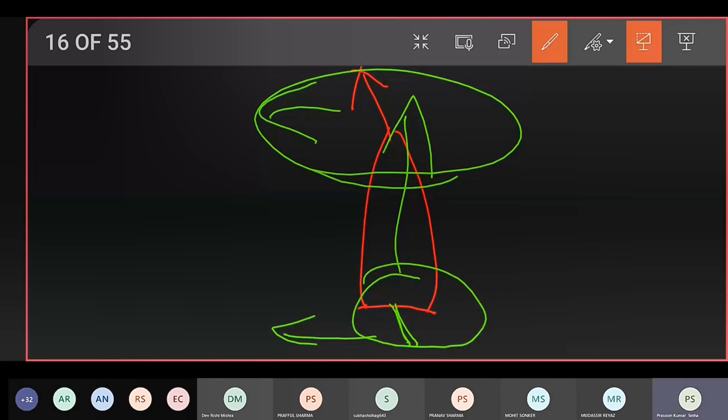So some bit of it is adopted by itself, but we also have our own input. We have manual control also for permanent helm. We'll see all the controls that we have available at our hand. अगले चैप्टर में देखेंगे. But the integral control reads the behavior of the ship, how she is behaving. Is she going again and again to one side? On the basis of that, the system will apply a permanent helm.